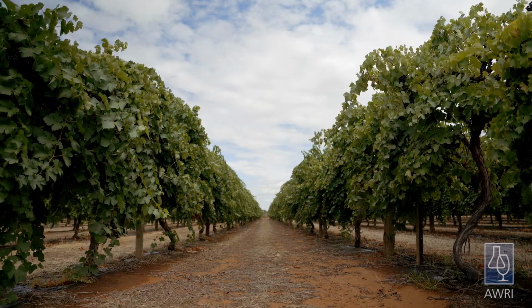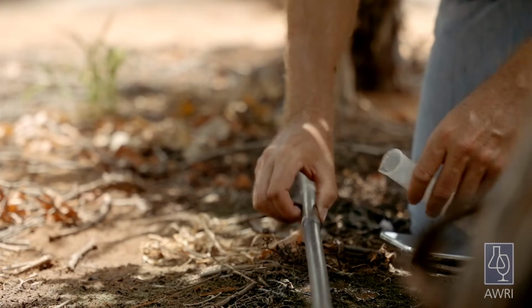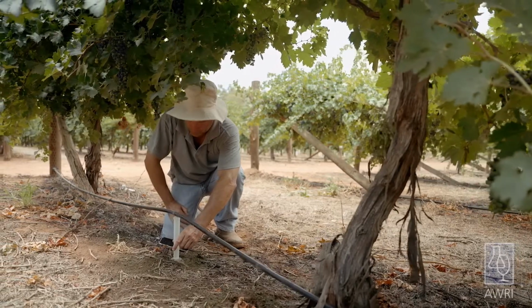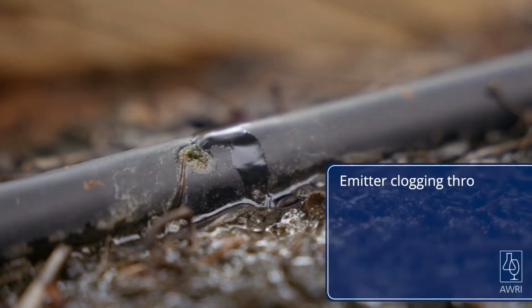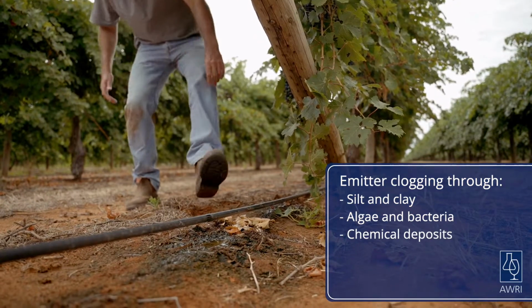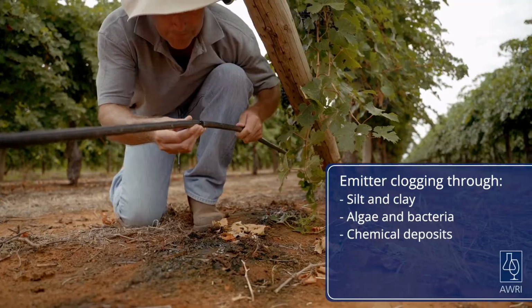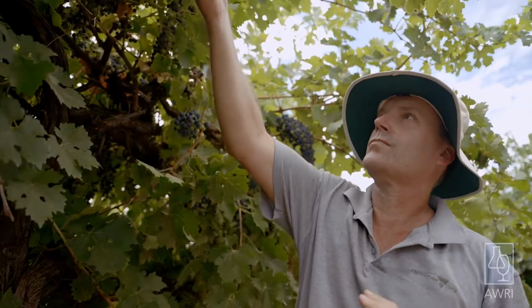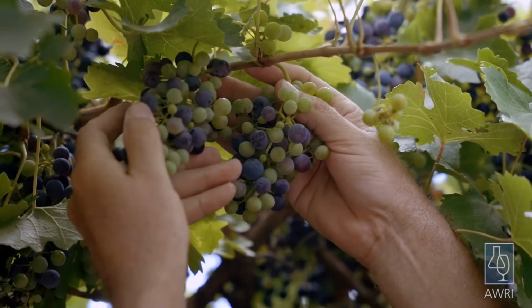Drip irrigation systems can be very efficient at delivering irrigation water to vines, but proper maintenance is essential to keep them performing well. A common problem is the clogging of emitters with either silt and clay, algae and bacteria, or chemical deposits. Clogged emitters will prevent vines from receiving the water they need.